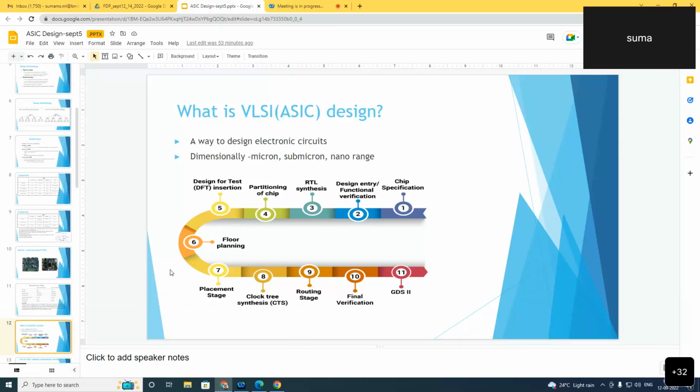What exactly is happening is, when we talk of the feature size of any semiconductor technology, it is defined as the minimum length of the MOS transistor channel between the drain and the source, and the technology has been scaling year by year. Scaling is nothing but reduction of size, and if double the number of transistors can be incorporated on the same area, it means we get approximately double the functionality for the same cost. Alternatively, with scaling of technology, the same functionality will be available at roughly half the cost.